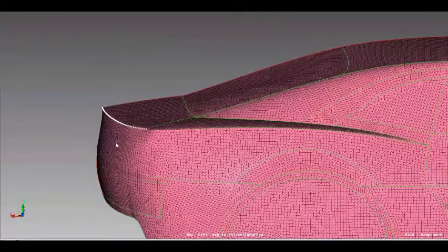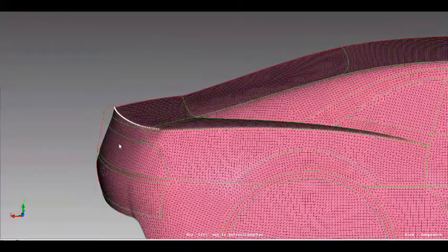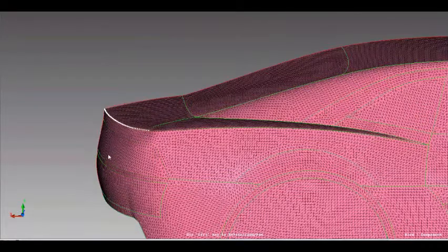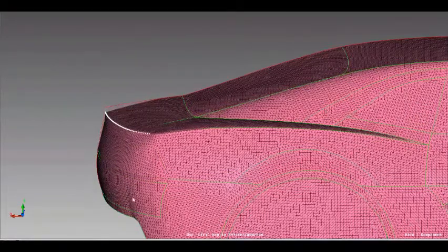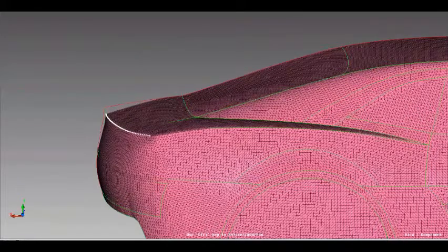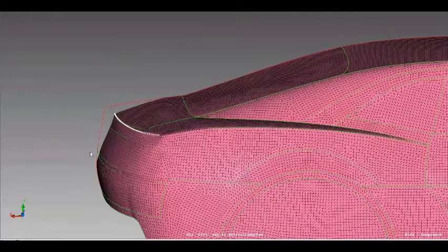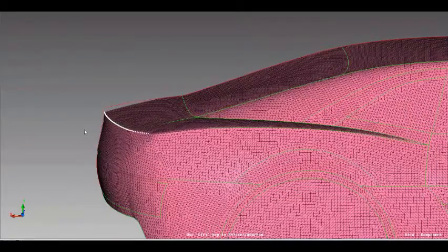And is this an option in the parameter definition, or is it after the morph set? Yeah, this is when you go to meshing and you go to translate. It's a one-time operation. You can link the morph set, and then you can move it back and forth, and you can accept it if you want. I mean, this is really useful. It saves a lot of time for us to create and visualize. Sometimes if we want to make any changes, we have to re-import the model and repeat the process. But this looks like it saves a lot of time, even before we define the parameter.